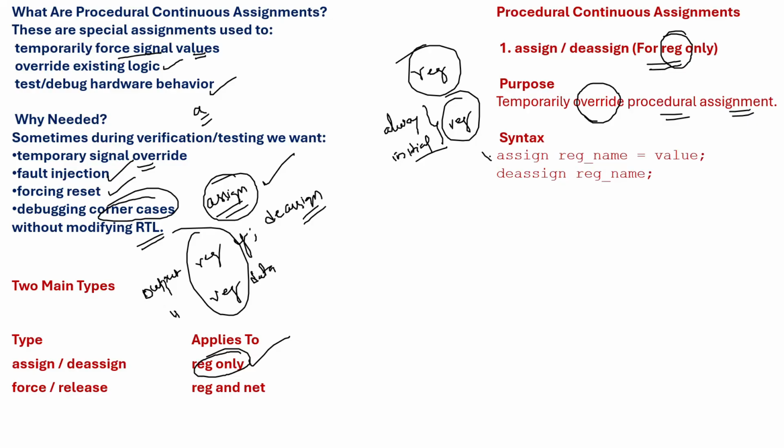So at that time I am not utilizing the assign keyword. The assign keyword is only for wire type. How am I saying wire type only? Suppose an AND gate, you can take input A, B. If you are not mentioning anything for the input, it will take wire automatically. Then the output Y I will also mention as wire. Then assign Y equal to A and B, right? In this way I will consider that.